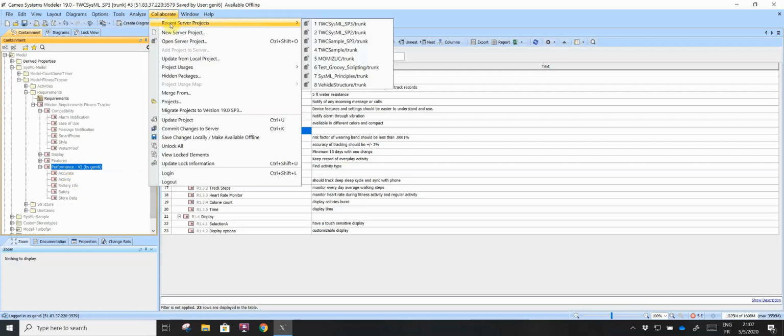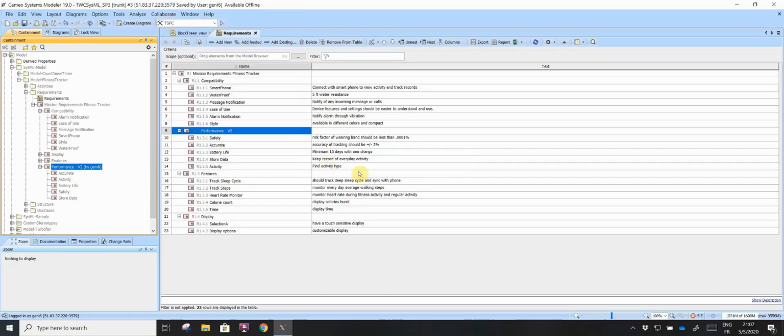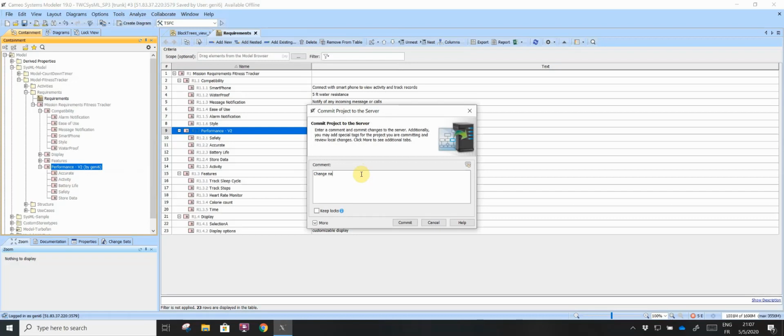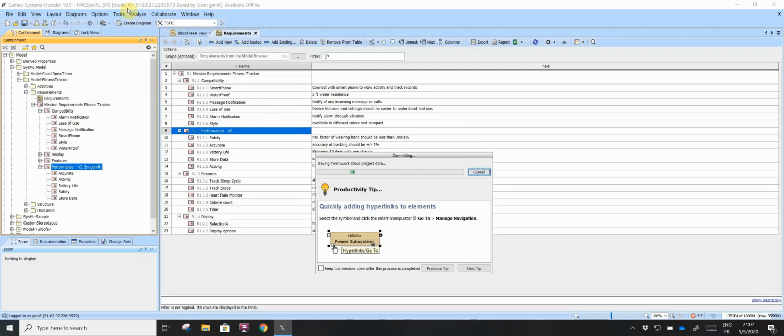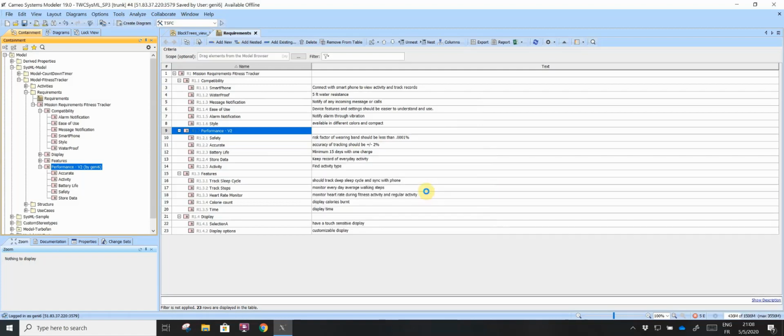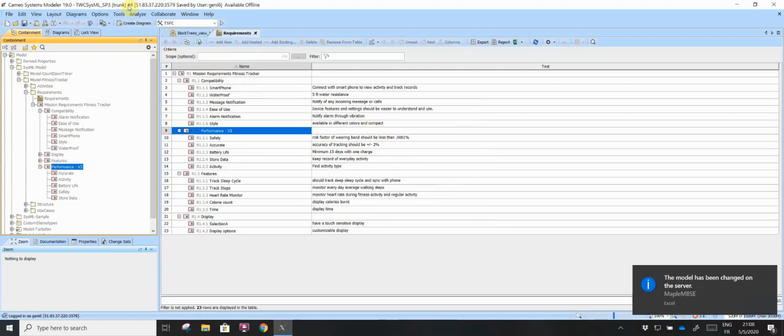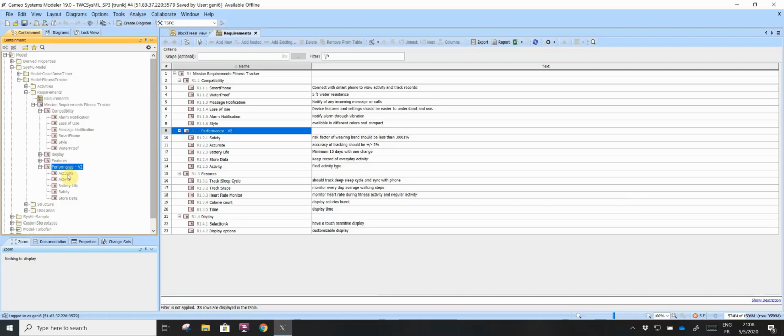So I open the commit window, I write down the commit text, change name for version V2, and I'm going to push the modification through that commit. Note that we are in version 3, I push the commit, and you will see that the version will increase by 1. So information is pushed in the cloud, and now you can see that we have switched to version 4. That means that the information is now available for any other user that is allowed to contribute on that central model.